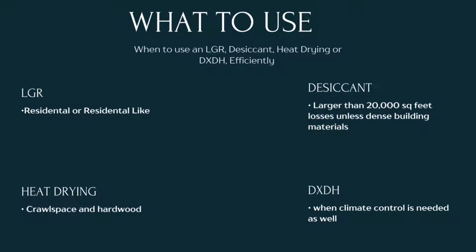In a normal house of 1,500 to 2,000 feet, you can use something like a 400 to 500,000 BTU indirect fired heater, duct it into the crawl space, and it'll blow the dirt dry in a fairly quick method. If you're using that method for a crawl space, if you're putting in 500 CFM, be sure to be pulling out 500 or maybe just a touch more CFM, because you don't want to put a crawl space under positive pressure and send the contaminants that are normally found in a crawl space, the musky smells and odors and that kind of stuff, up into the living area of the house. So you need to keep that under neutral pressure at worst, and a little bit of negative pressure at best.